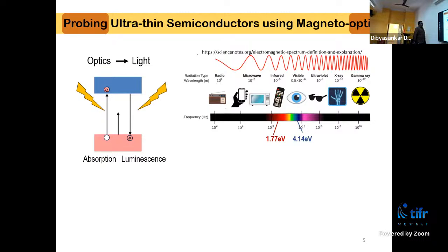And then one more thing can happen. If you are not giving that much energy, you are giving less, then the electron has no place to go, because the gap is blank. So it will not absorb, and that light will transmit through the system. It will not be absorbed. And there will always be some reflection from the surface. There is no surface which is perfectly non-reflecting. We artificially make surfaces which are not reflecting, but realistically, all surfaces will have some percentage of reflectivity.